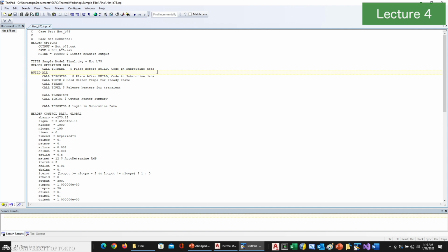So let's say I do a launch analysis and I drop away the fairing. So I could do the launch analysis up to the point where the fairing jettisons and then rebuild again without the fairing submodel, and it's going to keep all the states from everything else besides the fairing. So a way to manage different configurations that are here. You could also use it for building different sets of radiation couplings. You know, I want to do a deployment analysis, so let me do my stowed case, rad case, and then rebuild with my deployed rad case, for example.